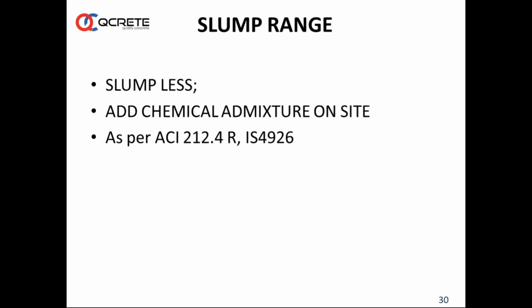We have a slump booster. Here we also need to understand that a Class F type of admixture has to be used. Many ready mix producers don't go for a different admixture for addition on site, but it is ideal to use a Class F type of admixture, where there is no retardation effect.